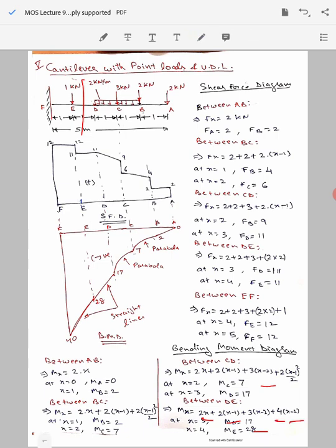Now let's go on and plot the value of bending moments that we have obtained from this equation. This is straightforward. For point A it is 0, so we start from 0, and you see this is making a drooping shape, and we have assumed that drooping shape to have the negative notation, so we'll plot all of these equations on the negative side.